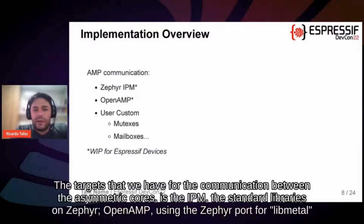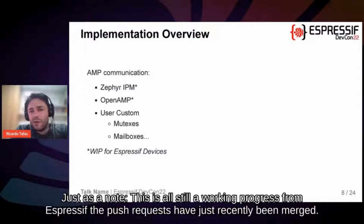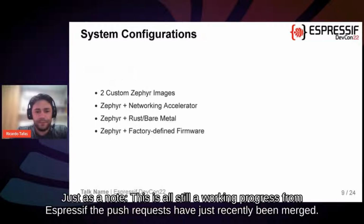So the targets that we have for the communication between the asymmetric cores are the IPM, the standard libraries on Zephyr, Open AMP, using the Zephyr port for libmetal, or users can use all the resources they want to exchange data, and we have then mutexes, mailboxes, and all of that. Just as a note, this is all still a work in progress from Espressif. The pull requests have just recently been merged.